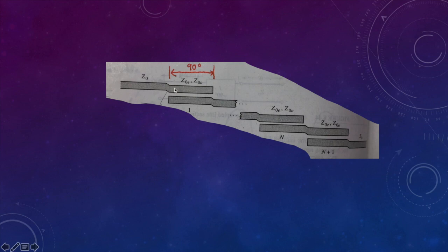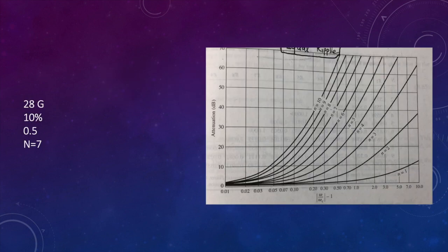As for these two microstrip lines and the air gap, they can be regarded as a planar waveguide. So we can use the planar waveguide to calculate the impedance of this microstrip line when it's working at even modes or odd modes. As for how to settle down what the impedance should be, we can use some equations.